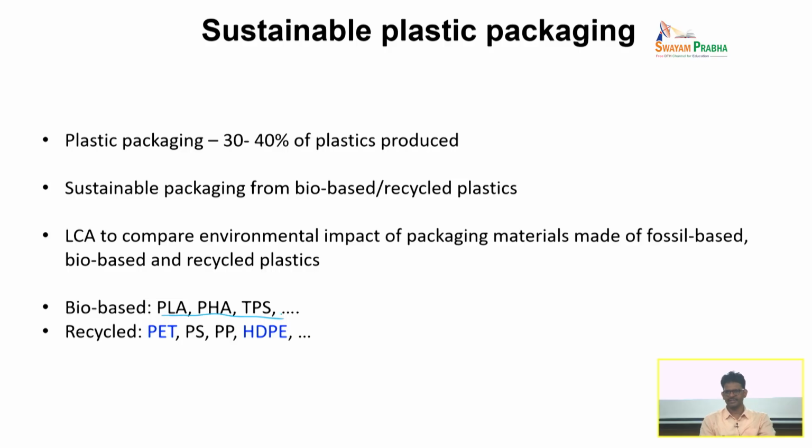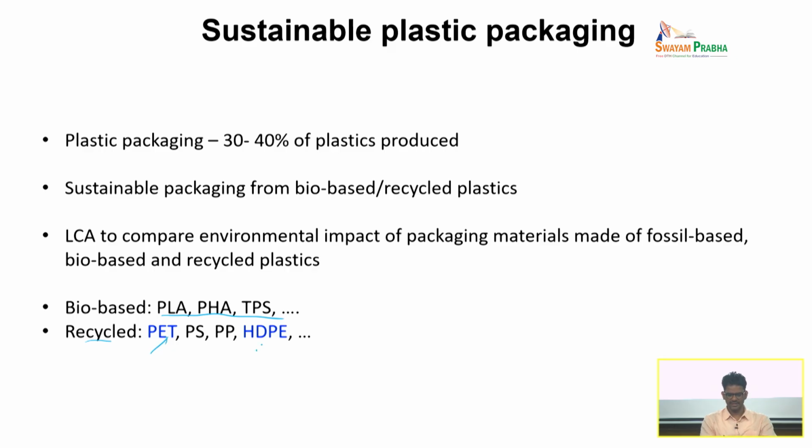So here is some example. If I'm thinking about bio-based polymers, then we are talking about PLA, polylactic acid, PHA, polyhydroxyalkanoates, TPS, thermoplastic starch. And then if you think about recycled options, we have recycled PET, recycled HDPE, and to some extent polystyrene and PP also. So these are all petroleum based products, but still if you have a good strategy to recycle this, you can also put it back into use. So when we do LCA, we are trying to compare, if I make a container with PLA versus PET, or PLA with recycled HDPE. So you can make different combinations and then you can look at what are the best choices for us.